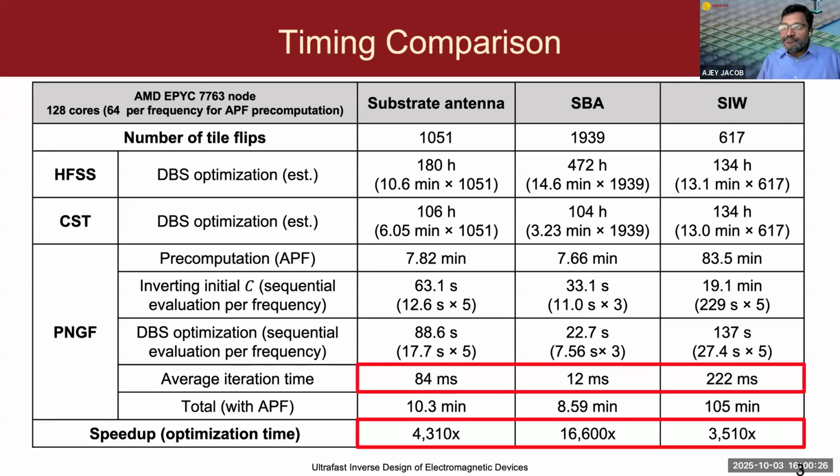So I apologize if I'm starting to sound like a broken record, but curved structures are more challenging with finite difference methods. But if you use a mesh-based method, like a finite element method or a method of moments, where you don't have a structured mesh, then you could represent those fairly readily, and you could have curved structures without problem. You just need to discretize the curve. You can use curvilinear elements if you want. We haven't done that, but you can do that. The majority of solvers, including HFSS and CST, essentially just discretize the curves in terms of piecewise linear segments. You could do that as well, to whatever fidelity that you need.